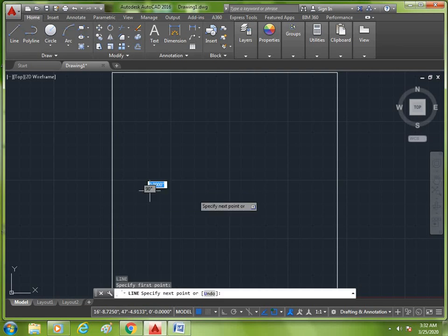So if you make a line, L enter, and then I want to make another line, this is the starting point, this is the middle point, and this one is the end point. So after the object snap settings, it will guide you on how to draw another line properly at the end, middle, or starting point. So these settings are important. Before making any drawing, you must confirm the fixing of these 4 settings. Then you can easily make your drawing more precisely, accurately, and with proper dimensions.